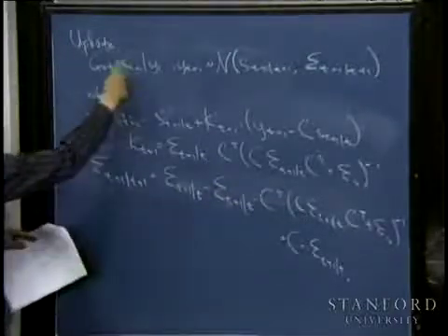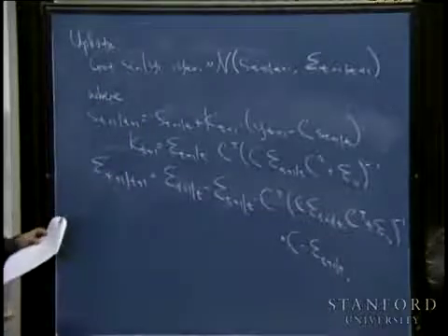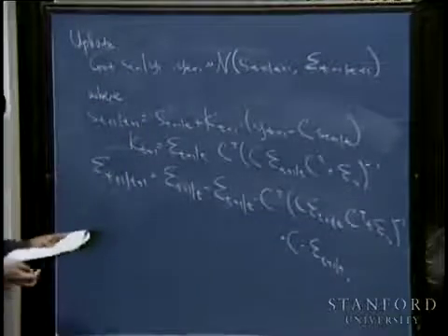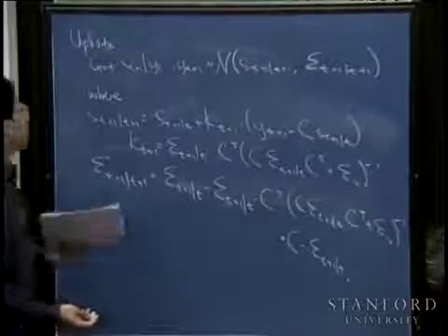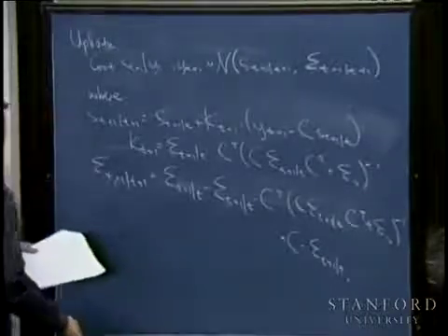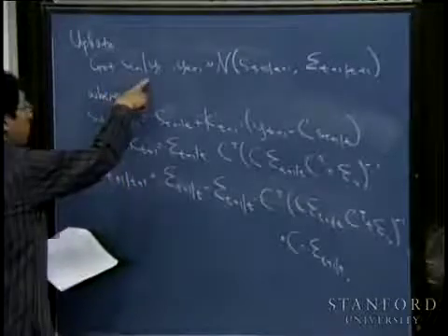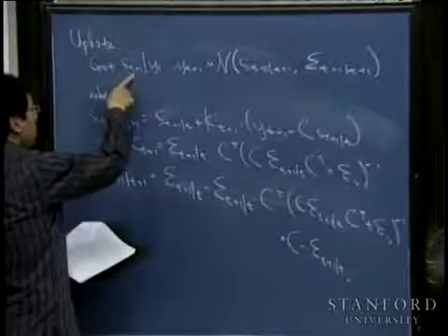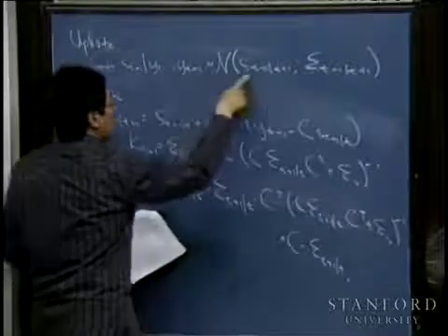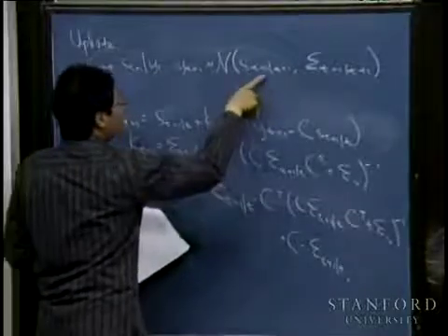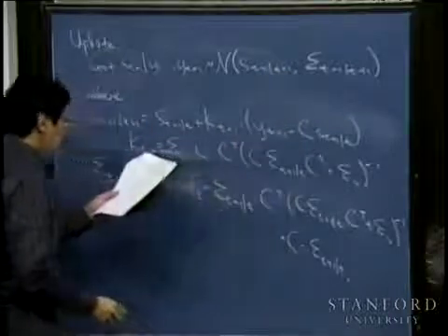We compute this in terms of your st given y1 through yt. And so, after having performed the most recent Kalman filter update, you find that your posterior distribution on the estimate of st plus 1, given all your observations so far, is Gaussian with mean given by this and variance given by that.